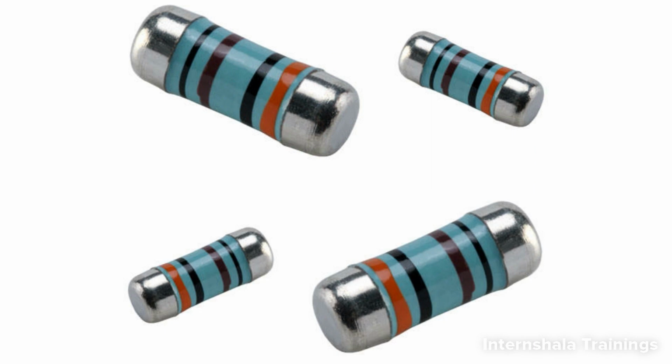MELF resistors consist of a metal alloy material and are considered better than typical SMD resistors in terms of power rating and stability under high temperature environments, but they are more expensive and cost more to assemble due to the cylindrical shape they have.